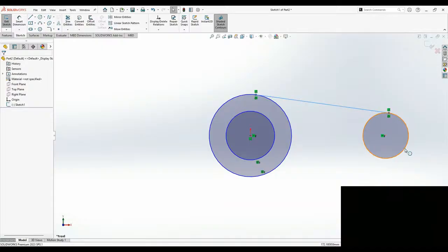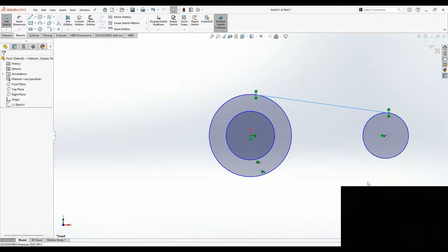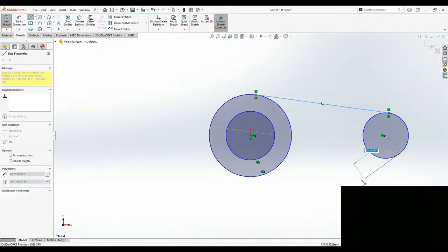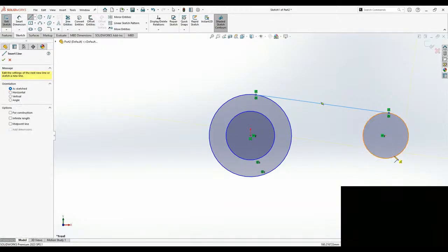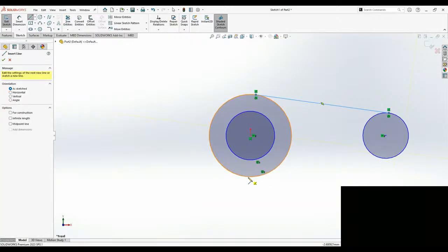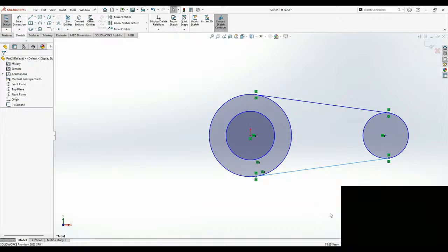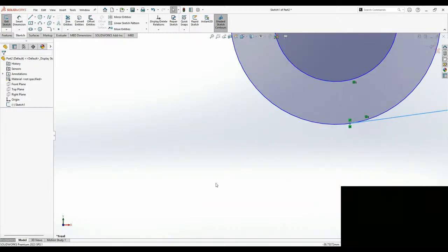Agreed. Now similarly again I'll activate the line tool. I'll click here. Nope, it took the point directly. It should be somewhat near here. Sometimes it does like this. Yeah, now this is fine. Just hover on this, and once you have the tangency, just click. Right? Now, I'd like to show you a few advanced things in